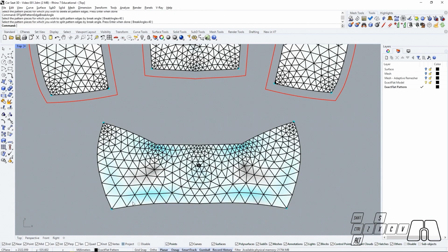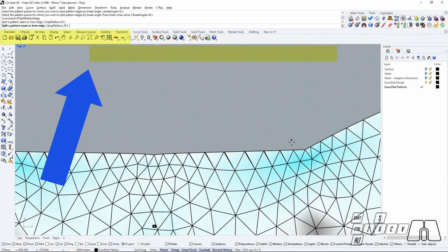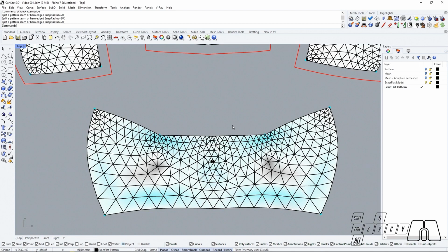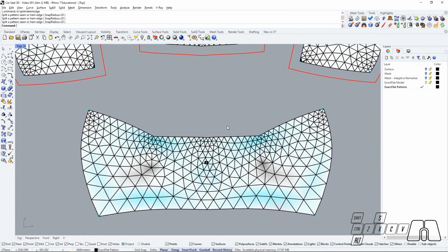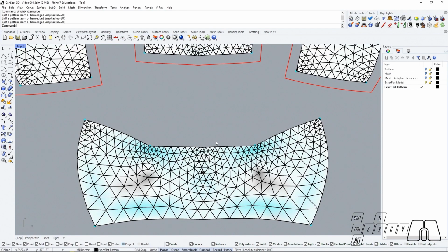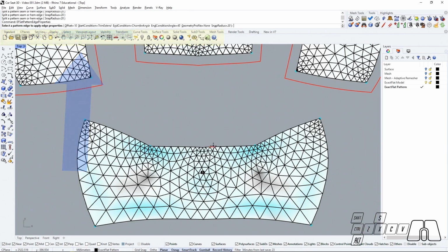and add some automated split points. And in this case, we could be applying some more splits over here. By default, our ExactFlat edge splits are going to be applied wherever ExactFlat detects that you have sewing line. In this example, ExactFlat was detecting different sewing lines because of the way in which this model was originally set up. So now that we have applied our edge splits, we can continue setting up our seam allowances accordingly.